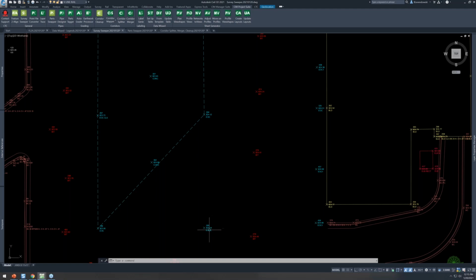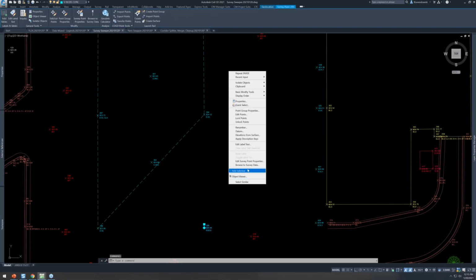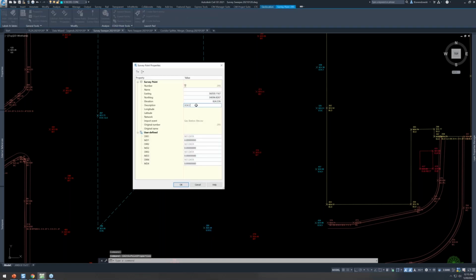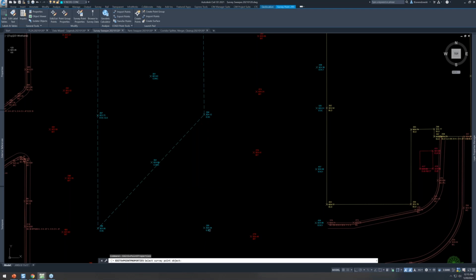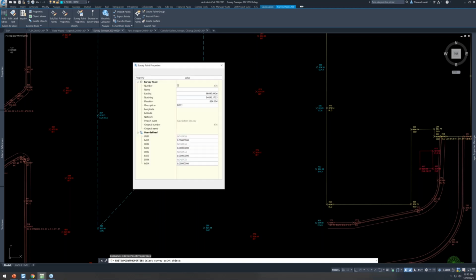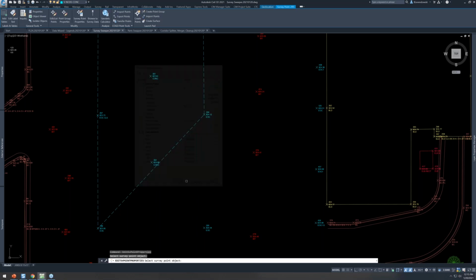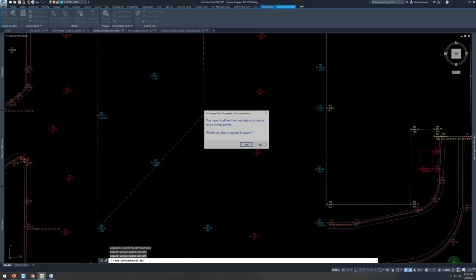And the nice thing about Civil 3D is we can take that information, and if something was miscoded, I can change the survey code on it, okay? That one that had two C's, and for that reason, this concrete pad didn't connect in that corner. That's my automatic line work, my survey figures there. And then over here, I was perhaps supposed to have another edge of concrete line, but the surveyor just happened to forget to put the B code in here. Now, this is all native functionality so far.